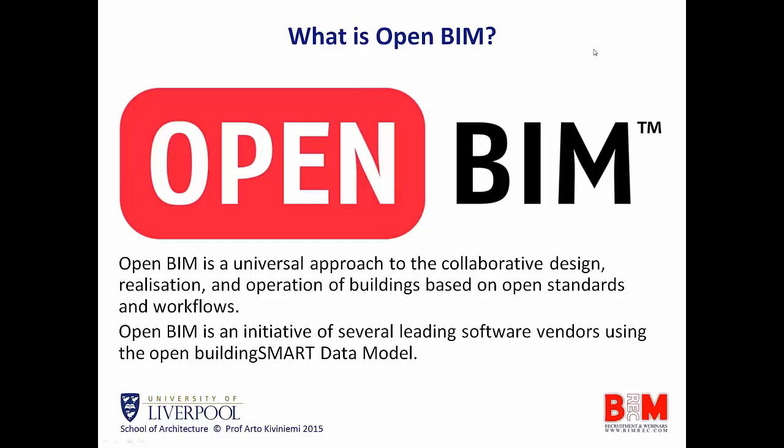And then when thinking about what is really Open BIM, I took some definitions, and I'm not going to read all the text that I have in some of my slides, but the main thing there is that it's a standard, a common language for the BIM software, so that we can share the information that we create in different tools and reutilize that information in the processes using different types of tools. And the most common Open BIM standard is based on the Building Smart Data Model, IFC, Industry Foundation Classes.